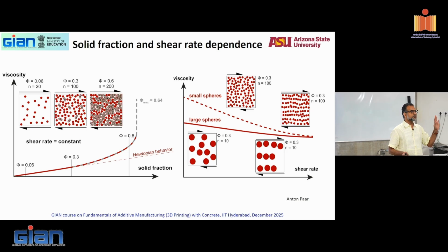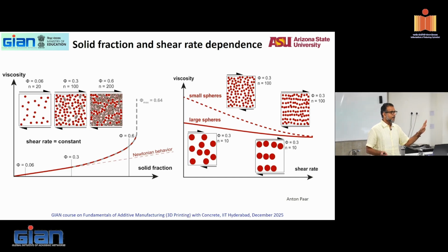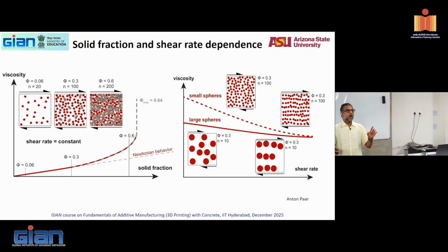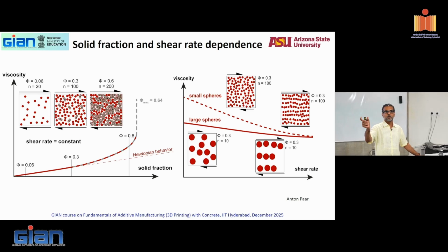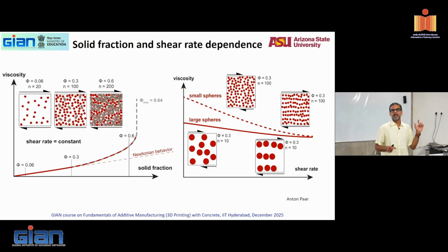Water cement ratio of 0.4 is roughly equal to a volume-wise solid fraction of, water to cement ratio of 0.4 by mass is equal to about 1.26 in volume, right? That is water to solid 1.26 by volume, or 1 over 1.26 solid fraction. Get the idea? Kind of roughly.